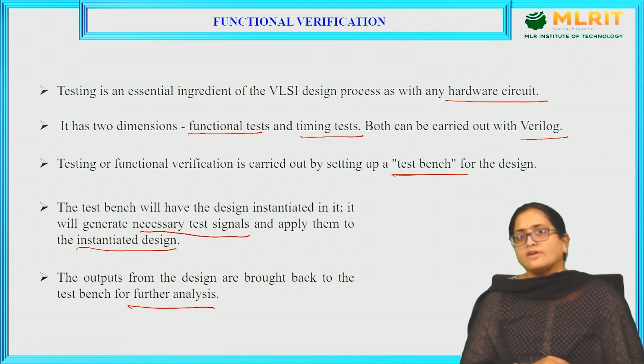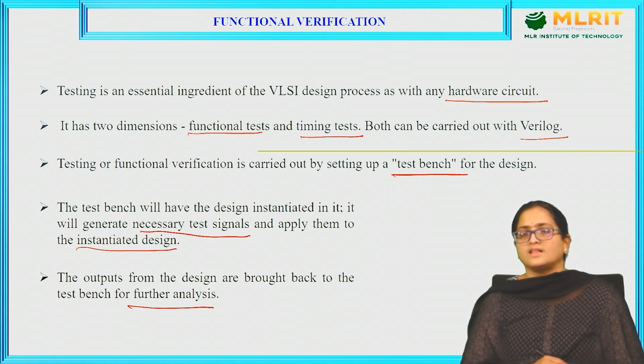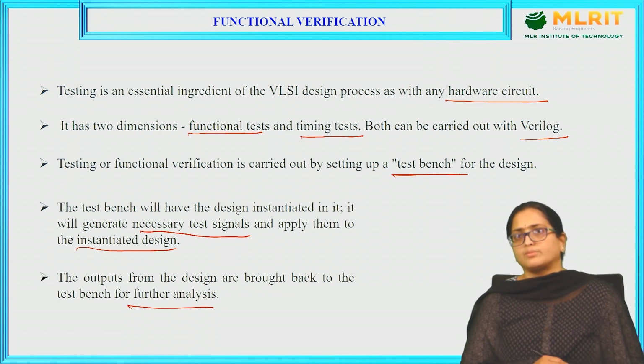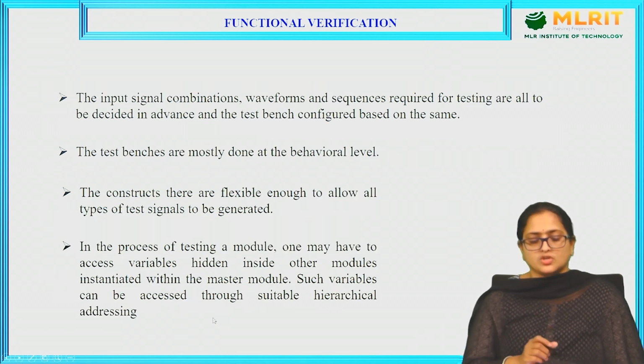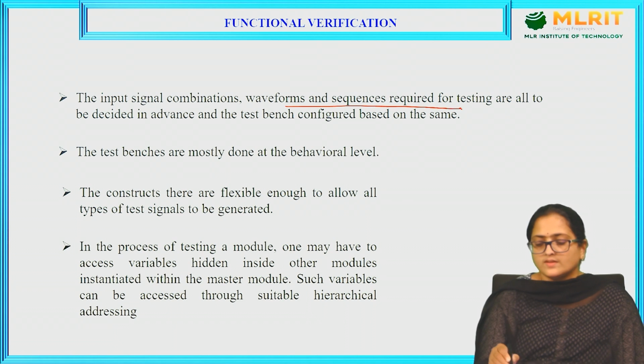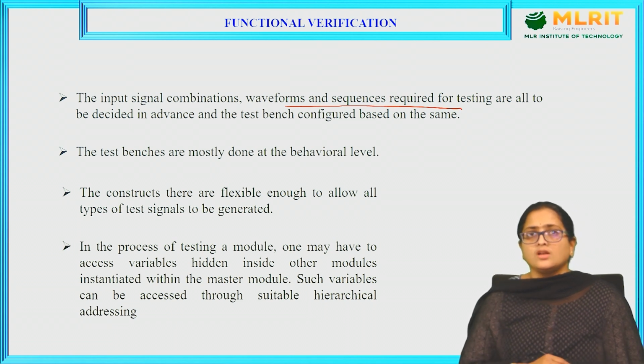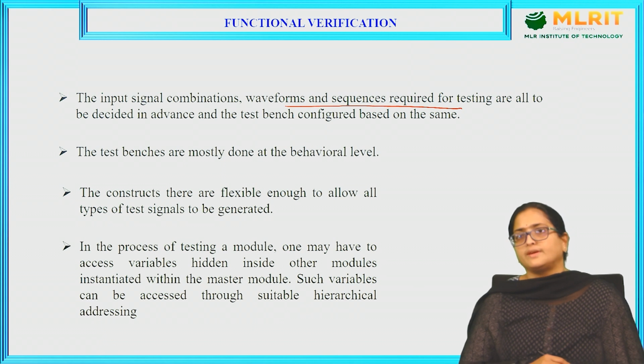So each and every Verilog code can be tested by using a test bench code, where the necessary test signals can be applied directly to the instantiated design, and the outputs can be analyzed for multiple inputs. The input signal combinations, waveforms and sequences required for testing are all decided in advance and the test bench configured based on the same.